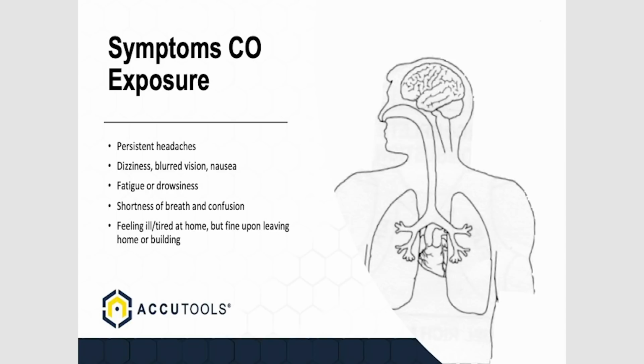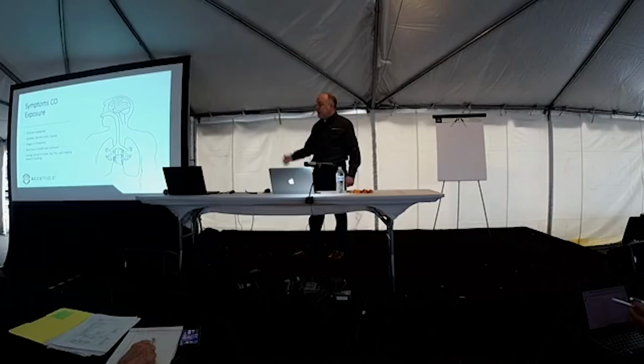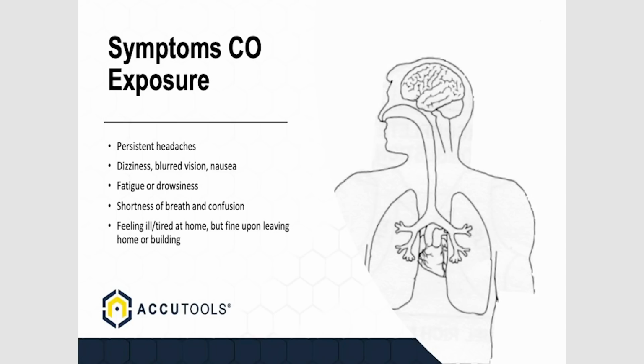You guys, when you walk into areas, should be aware of what you're walking into. Years ago, when I was about 19 years old, I walked into a flower cooler that had a dirty evaporator coil. So I go in with my tank of CO2 to blow that out, and I walk into this little, maybe 8 by 10 cooler, and I start blowing it out with CO2, and all of a sudden I'm starting to get really dizzy. I'm thinking, what the heck's going on here? And I realize I'm displacing all the oxygen in the room, right? Those are simple mistakes. It's the same thing here. You walk into a big boiler room, and we've seen some pretty big stuff dumping CO in spaces where you come back after lunch and you think the Chinese got you, and again, you're exposing yourself to CO.